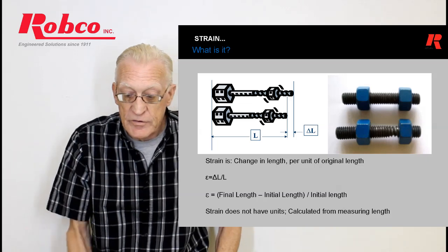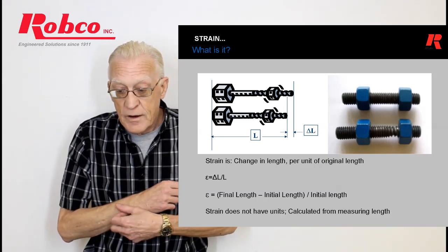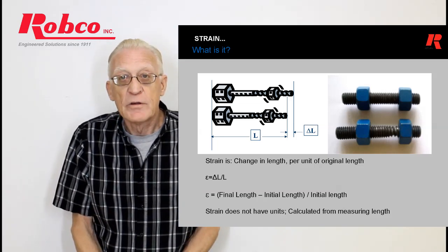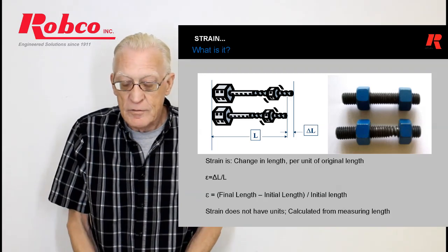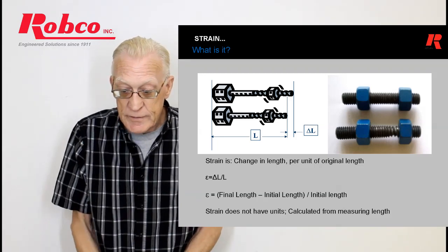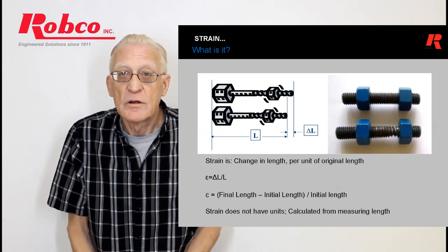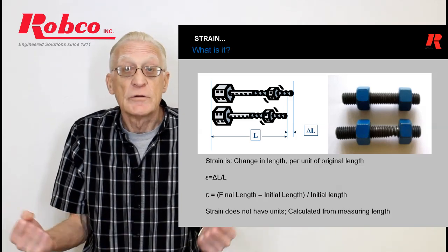Here's a better example. There's a gasket, there's a bolt, or a stud in this case. And look what happened to the spring that it was. They over-torqued and over-torqued and over-torqued, and they just pulled the whole thing apart. It takes a lot of power. It takes a lot of foot-pounds of torque to be able to take a piece of metal like that and stretch it.